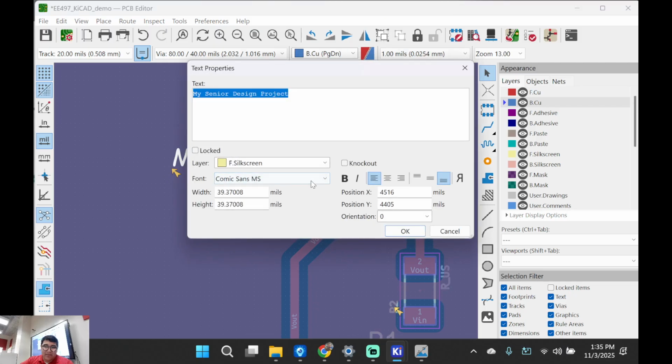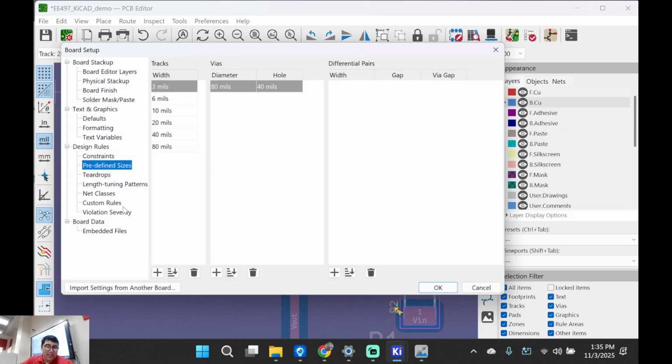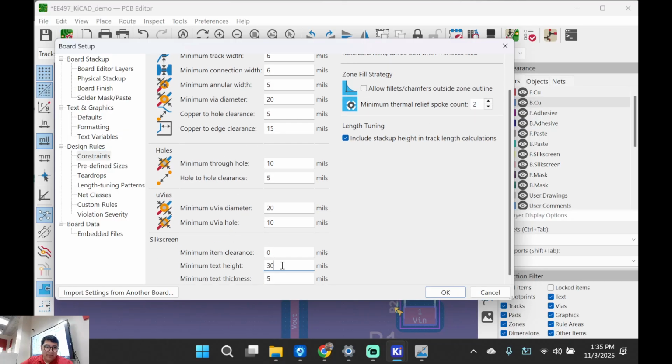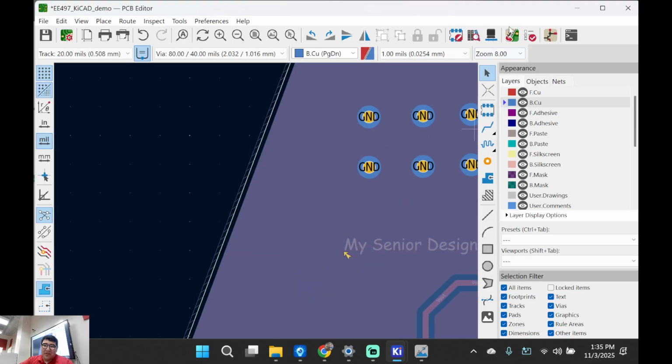My senior design project. You can edit it right here. Board setup. Constraints. Text height. 30 to whatever. 20. Run DRC again.